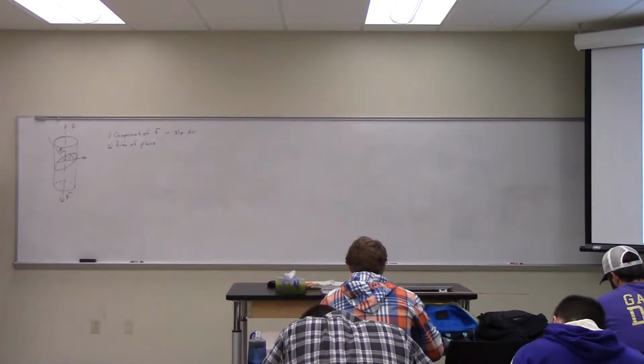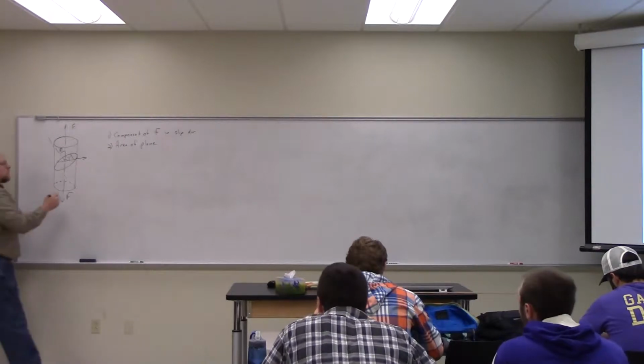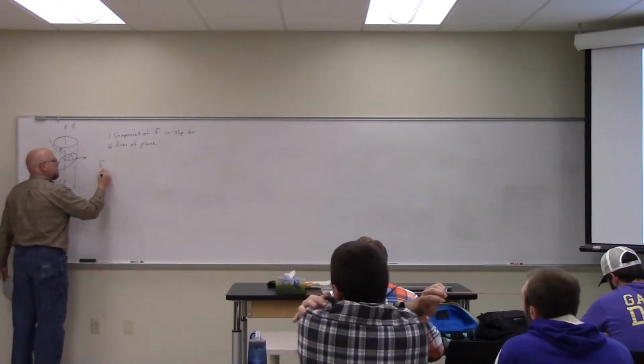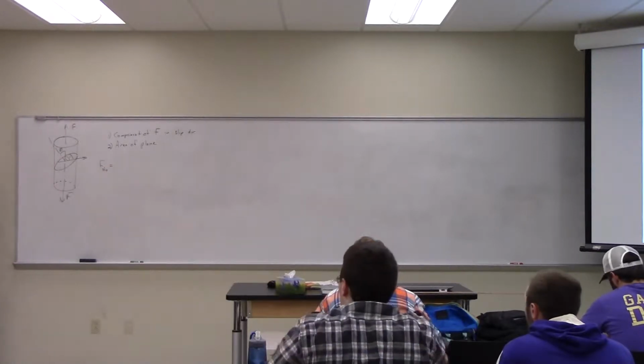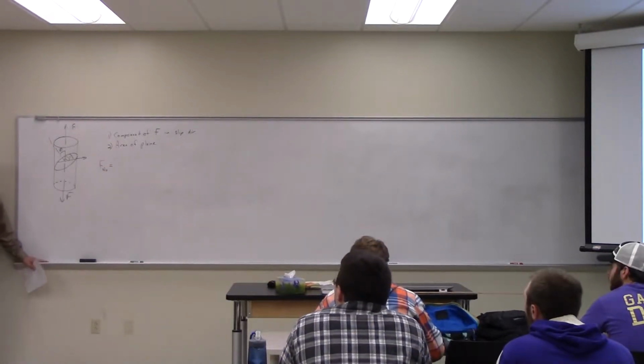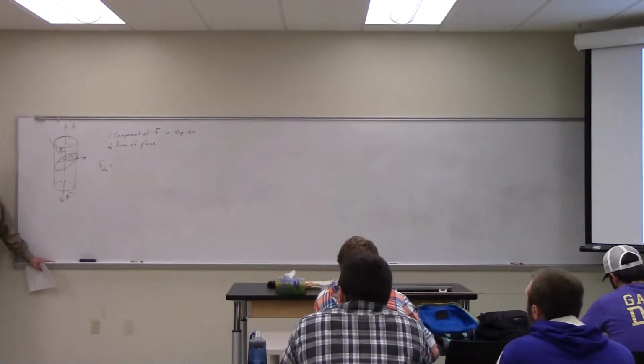So what's the component of force acting in the slip direction? It is not F sine of phi. It is F cosine lambda.